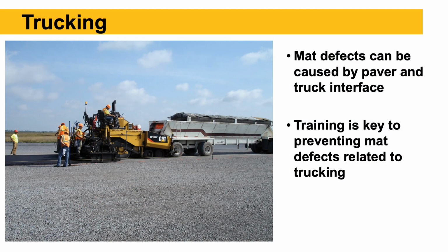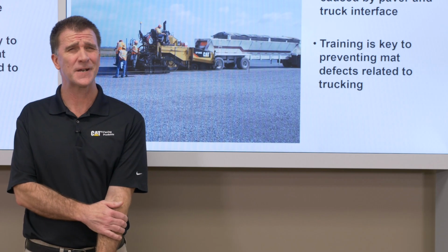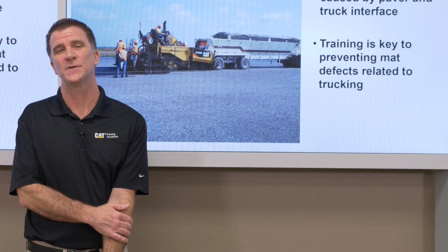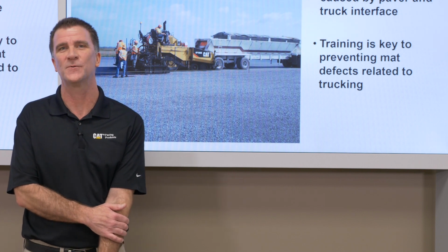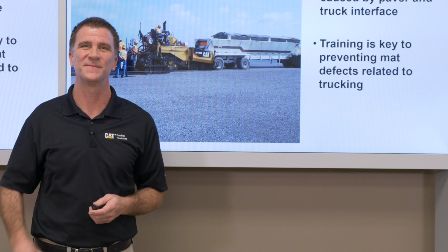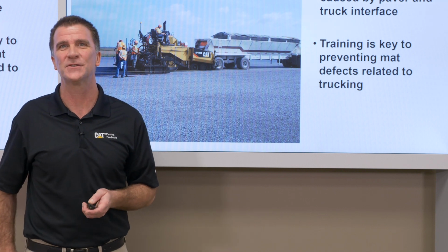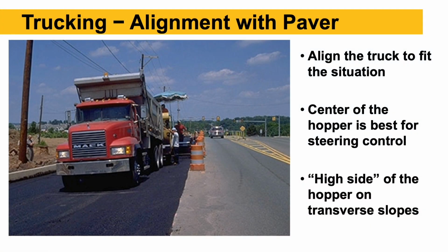Trucking mat defects can be caused by the paver truck interface. So again, mix delivery here is what we're talking about, and a constant paver speed. So training is key to preventing defects related to the mix delivery or trucking. We don't always do the best job of training truck drivers, do we? A lot of times we just kind of like to bark at them when they're not doing things right, but we don't spend the time to show them or tell them what we want.